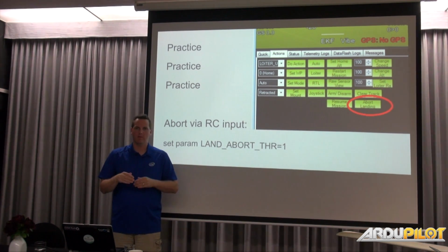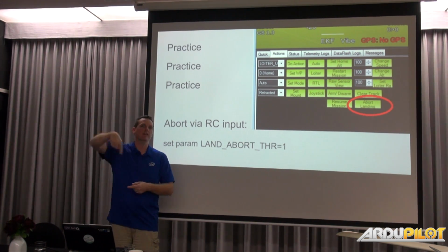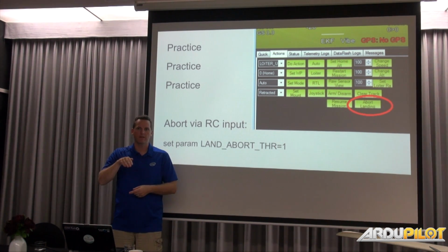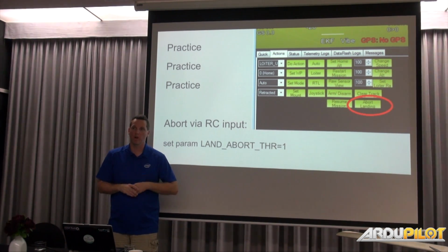If it's too steep, depending on what that barometer is set to, then you can just abort, remember what that offset was, fly back around, and then you're actually coming in with that compensation already applied. So it'll automatically do all that for you with no hands if your barometer has drifted a lot.